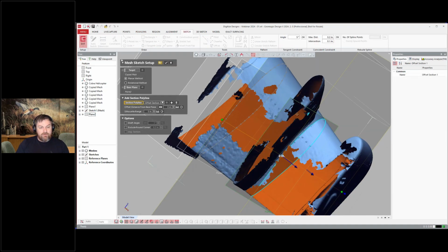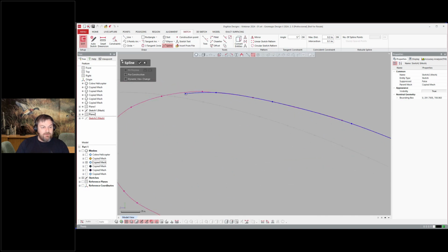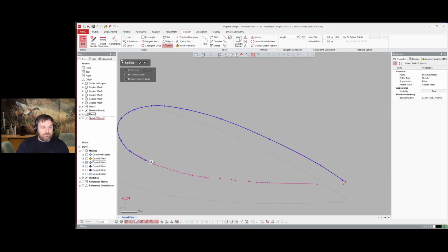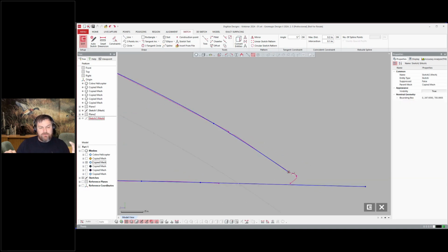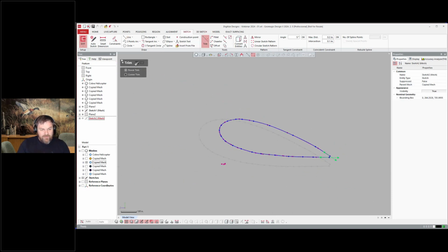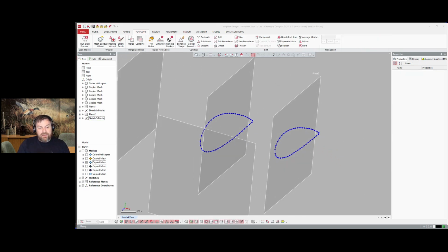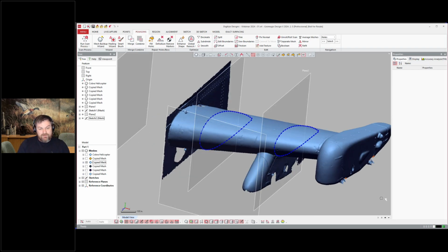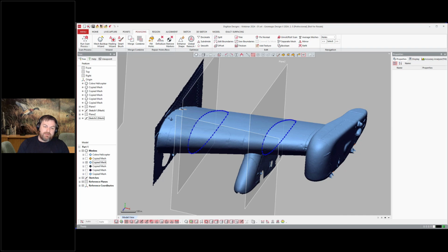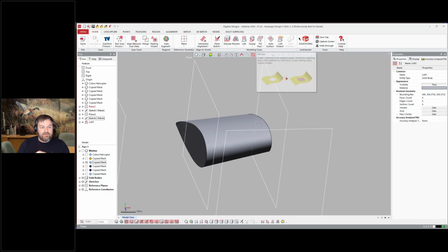You can see here that I'm just going to create another mesh sketch in this instance and do the same thing. And that pink line is this cross section from the scan data. Now, the first one, I used a fitting algorithm where I just grab the spline and best fit a spline. And sometimes in these videos, I'm not doing everything the most ideal way. I'm usually showing that functionality exists, and this is how you can do it, right? So in this instance, the second cross section, instead of best fitting it, I actually drew it manually, snapping to what's there. So you see now that I have these two different cross sections, I'm able to come over here and say I want a loft between those cross sections and create a solid body there.